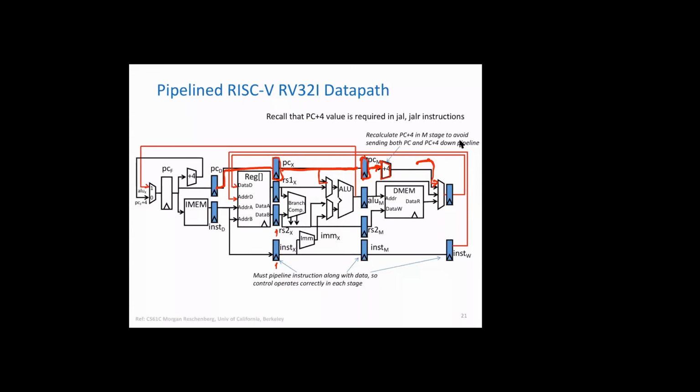So we have to say that each phase, or each part of the pipeline, has to execute different instructions. That's the reason we have to separate this out. It's kind of a separator. And as a result of that, of course, the advantage is that clock cycle time is reduced, because all you have to take care of is just a single stage in that clock cycle.